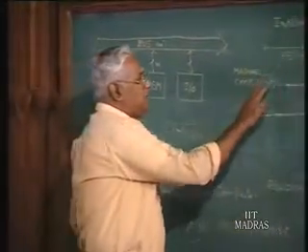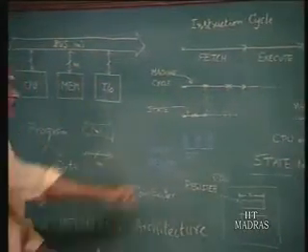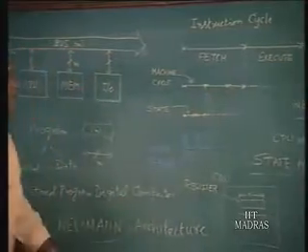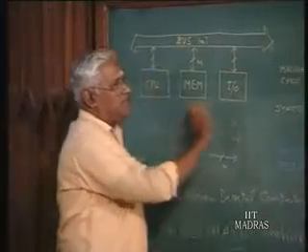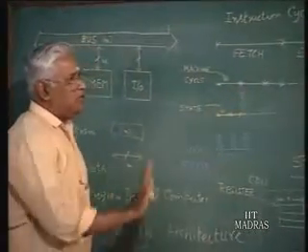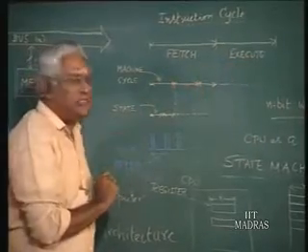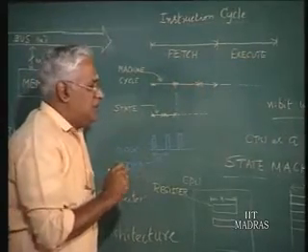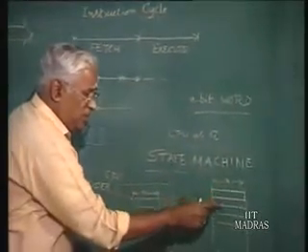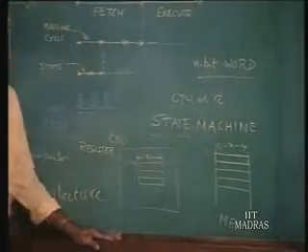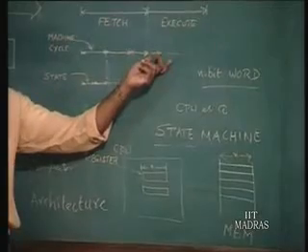So when we say that this particular thing consists of, here, 3 machine cycles, basically we are saying 3 times the CPU is accessing the bus. Now let's assume that as part of the execute phase you have an operand fetch, that's the data fetch, right? Suppose the data that needs to be fetched from the memory happens to be a 2 word, then during data fetch there will be 2 machine cycles.